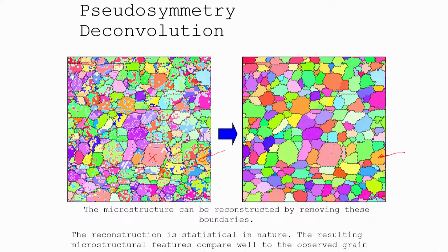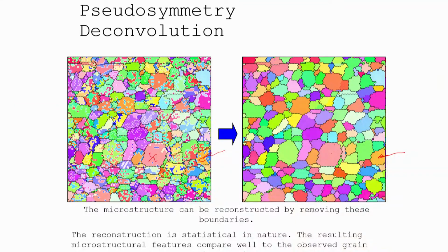Is it possible to identify by the band, like by the spacing? Even if it's a superlattice of a particular crystal structure, my d-spacing will be bigger. So with the superlattice, we can identify by that, but can we differentiate somehow? Even if the Kikuchi lines are superimposing, the band cut will be different, like the cone, the spacing will be changed. Yeah. So the question is, can we use bandwidth differences in indexing to determine whether there's a superlattice or not?